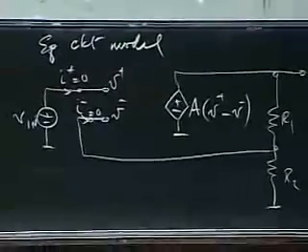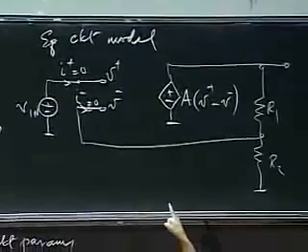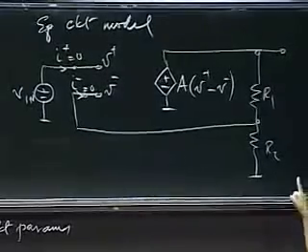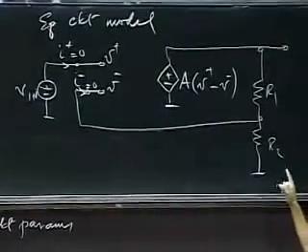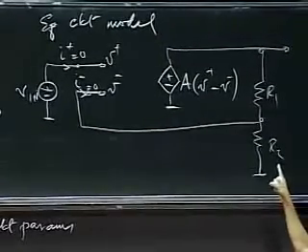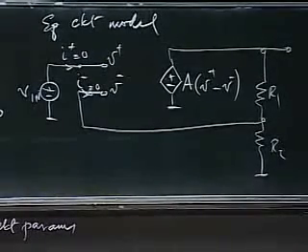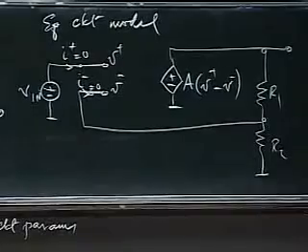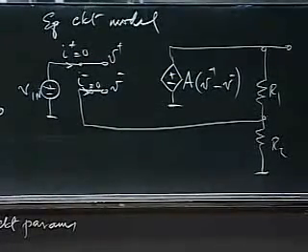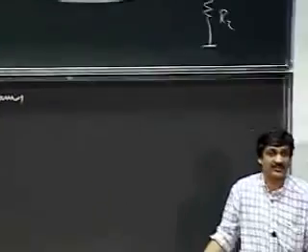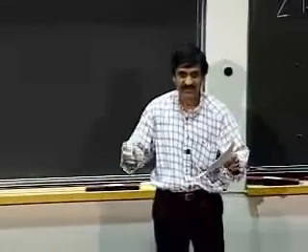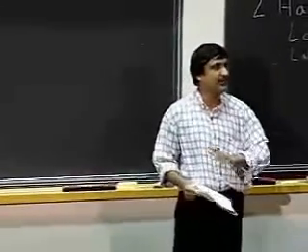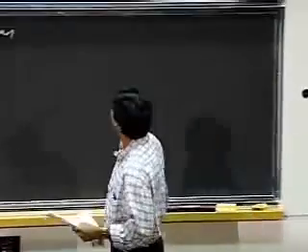So this circuit here, all I have is one unknown node voltage. I know the voltage is V plus. I need to compute the voltage V naught. So there are two unknowns: V naught is an unknown, and the voltage here at V minus is another unknown. This is a very simple circuit involving a dependent voltage controlled voltage source, and you need to find V naught and V minus using the node method. Just apply it, it's simple. Don't freeze, just look at it and say, I can do it, and apply the node method. It will simply work.